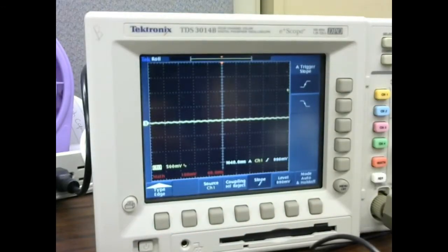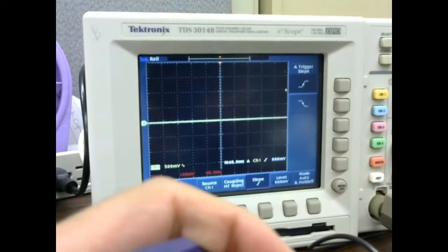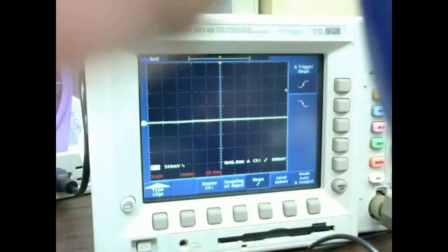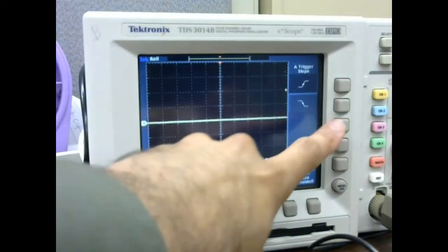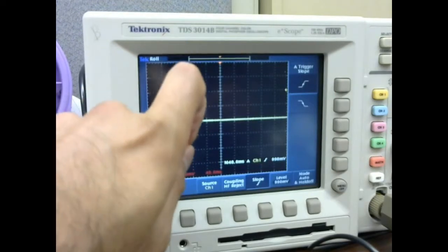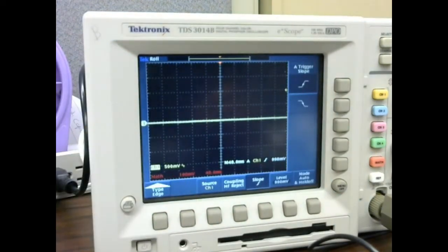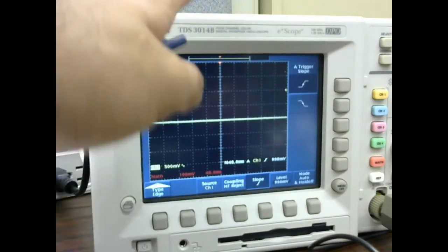So I have the piezoelectric material. I put the ground plug on. I'm touching it with the voltage probe. And you're sort of seeing my hand hit this thing. You've got to watch out for the trigger here, because if we squeeze the material, and the dot should go on the top, then the material is going to jump up to positive voltage.